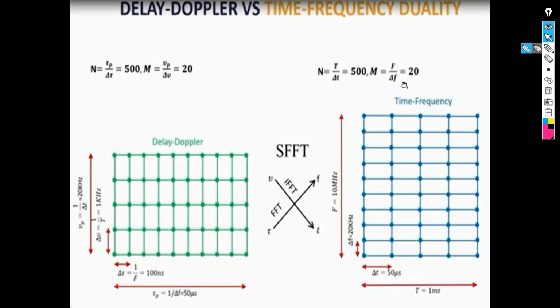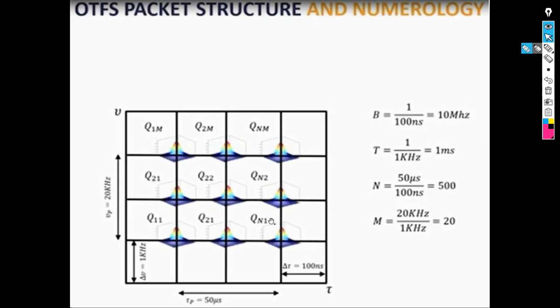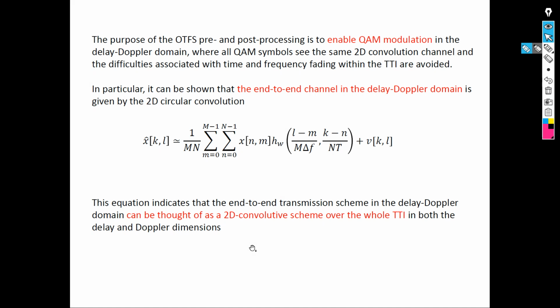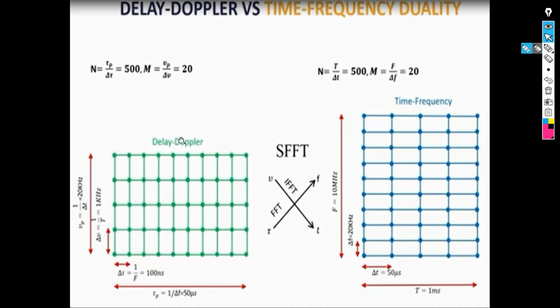Now you have delta T, delta F, subcarrier spacing, and so on. In delay Doppler, we didn't have something called Doppler carrier spacing. Now you get new parameters, a new definition, that can be exactly mapped to the previous calculations, one-to-one. So no worries about that, because they are basically another view of the parameters here.